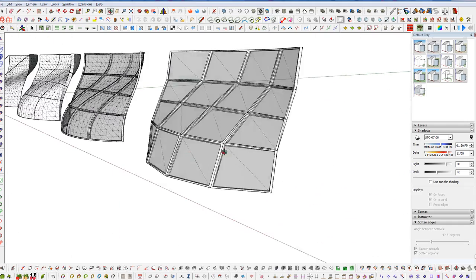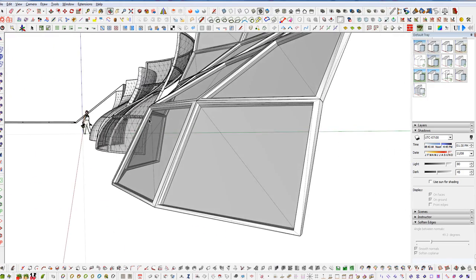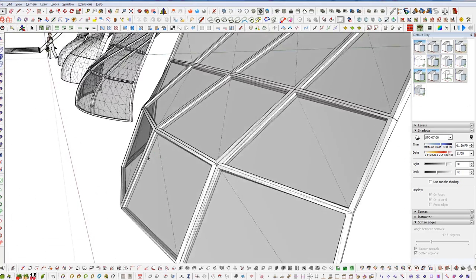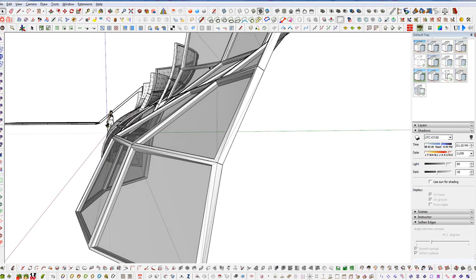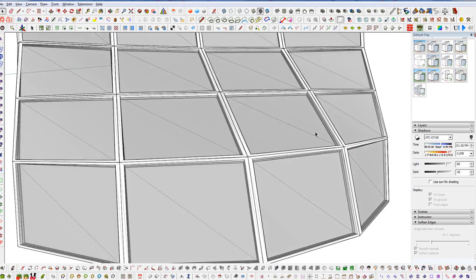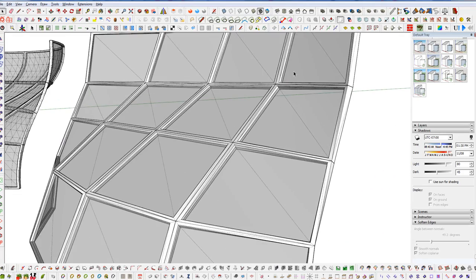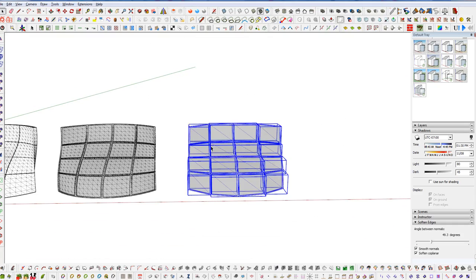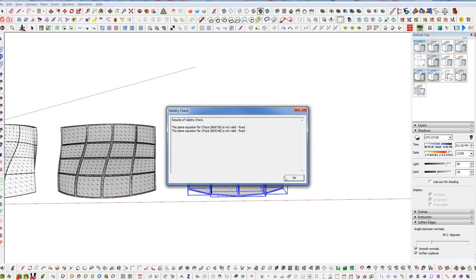Whereas here, we did the Flowify without cut, and all that did was a division down the center. So these aren't all necessarily planar. We can see that this is sitting a little bit skewed here, but in certain curtain wall instances, this would be a lot more realistic as far as the end result I'm trying to get, depending on how large the area is. So let's just run cleanup on this, and it didn't have anything to remove.